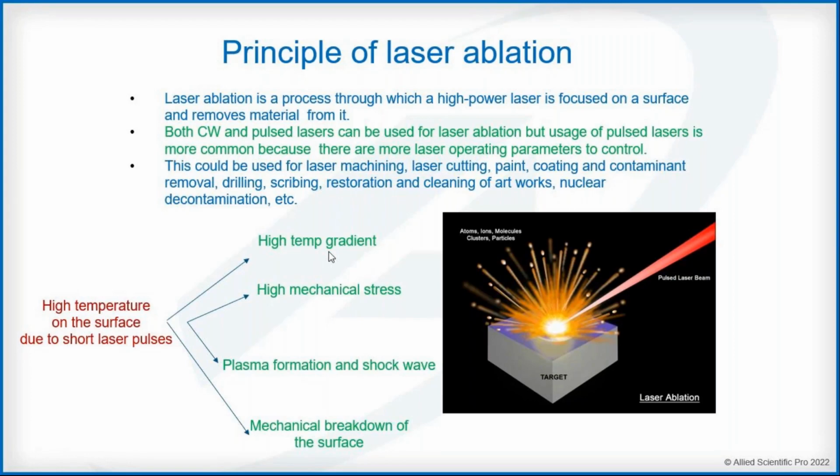Actually, both CW or continuous wave lasers and pulse lasers could be used, but we'll focus our attention on pulse lasers because there's more control over the parameters of the laser, such as pulse duration and repetition rate. All of these will affect the laser cleaning process, which I'll discuss later.